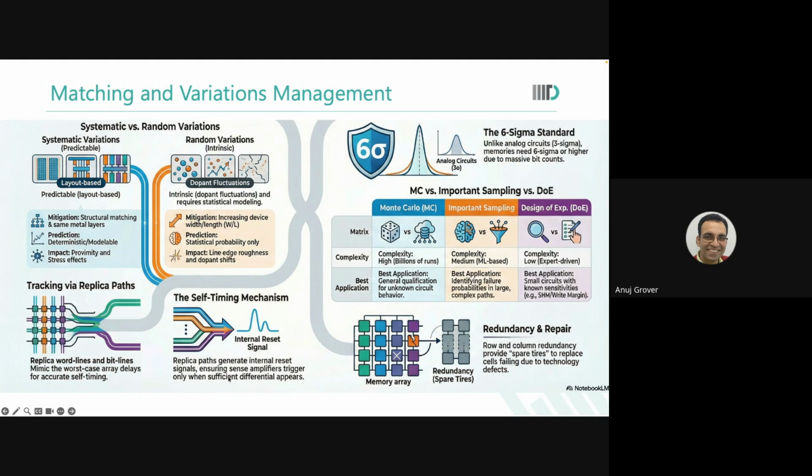Now tell me one thing. These scribe lines, would you want to think of qualifying Six Sigma there? No. In these scribe lines you can use very big size structures, because what do you need to measure? You need to measure how thick my gate oxide is. I wanted a current of this much to be flowing in the transistor at this time. Is it flowing like that or not? And these are big transistors, not very small transistors. It could be a range of transistors, reasonably spread out. And the count of such transistors is also not very high. Not just 2 samples, maybe 7 samples, 10 samples on a die, on a wafer.